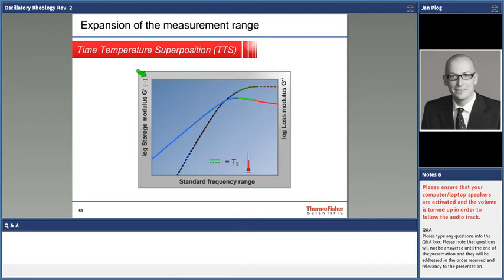When you know the polymer that you work with, you can use the viscoelastic response to calculate molecular weight and molecular weight distributions from the viscoelastic data. It's fairly easy, and in the polyolefin industry it is used more than standard GPC or whatever other approaches to molecular weight nowadays.